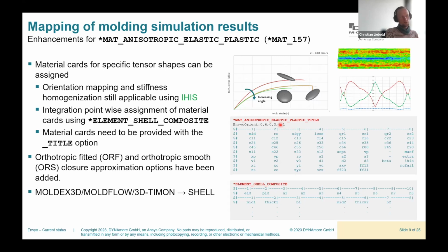And it also works quite reasonably from a mapping perspective, but also from a, let's say, result point of view. So if there's a good set of calibrated material cards, your finite element analysis might actually be even faster using that approach, because there are not as many lookups on the values on the integration point as if you would have a reduced amount of material data.